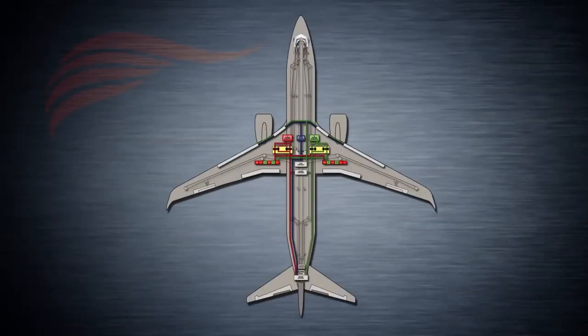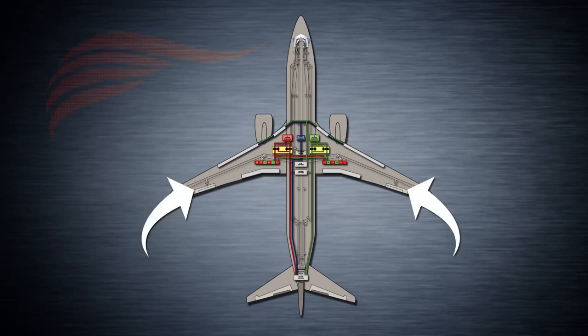Ailerons are movable surfaces on both wing outboard trailing edges that control the flight attitude of the aircraft about the longitudinal axis, more commonly known as roll. The ailerons are coupled so that when one of them moves down, the other moves up. There are 3 ways of achieving roll control on the 737NG. Manually, by moving either control wheel, automatically, by autopilot input to move control wheels with actuators, or through flight spoilers. These will be discussed at a further stage during this lesson.